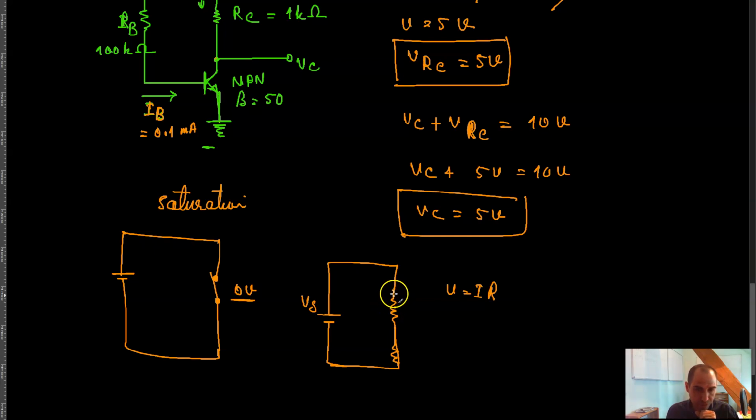But if the resistance of that resistor tends to 0, meaning that it gets closer and closer to 0, then of course the voltage drop across that resistor keeps decreasing, because if I keep the current constant here, by reducing the resistance, the voltage across the resistor has to come down as well, because this is an equation, right?